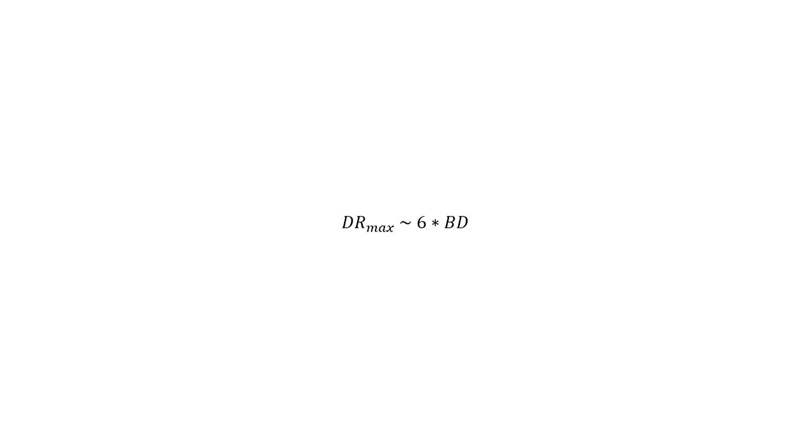What does 0 dBFS mean? One note of importance. Most DAWs will show you sound volume in dBFS for full scale with a negative value. Why? Because 0 dBFS is defined as the maximum capacity, the bit depth, of the AD converter. Thus, any sound will have a negative value lower than 0, which is the maximum.